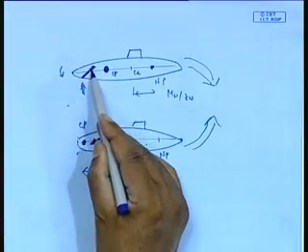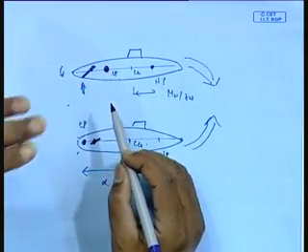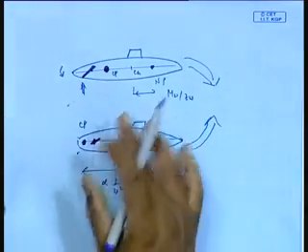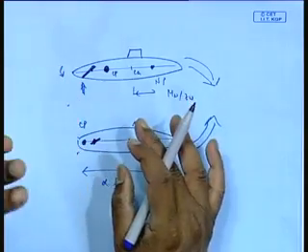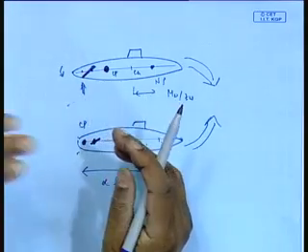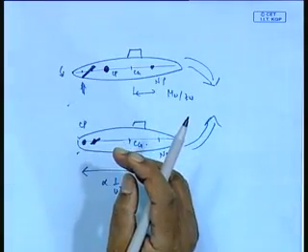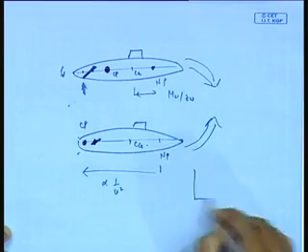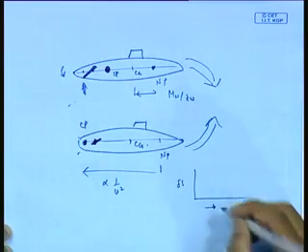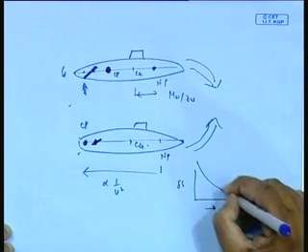Now, I come to a point where I give an angle, but it does not dive, it is simply giving a trim angle. That is the characteristic of the point, it is simply changing the trim angle, but not diving anymore. Now, I go further slow, and the point goes beyond that. Now, I give a dive angle and it goes the opposite side, goes up. So, if you plot delta S versus speed, the critical speed will come down like that.